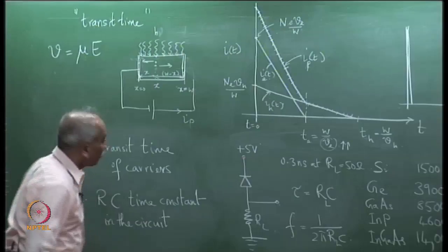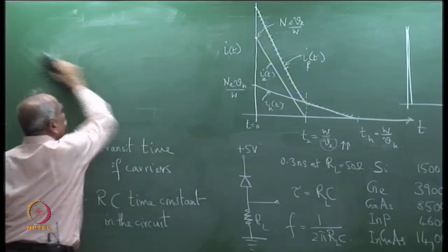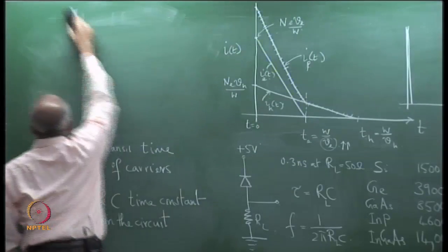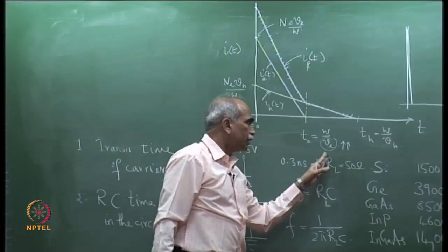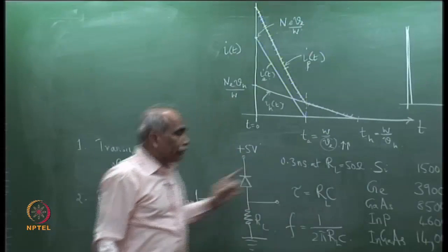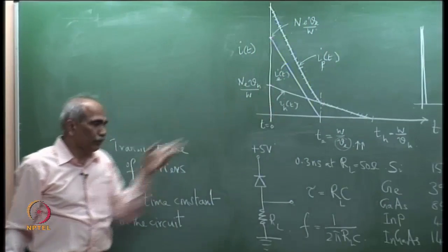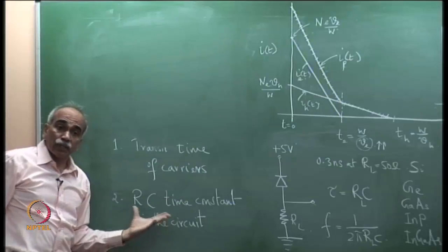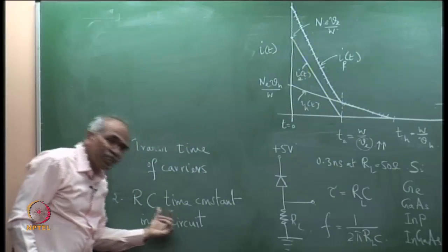This is very interesting. How does this drift velocity vary with the applied electric field? We have some time. So, if you take Ve very large and very small W, Te can be very small, and therefore this transit time consideration can be minimized. The impulse response is determined by two factors, transit time and the RC time constant in the actual system circuit, so that it is primarily determined by the latter.